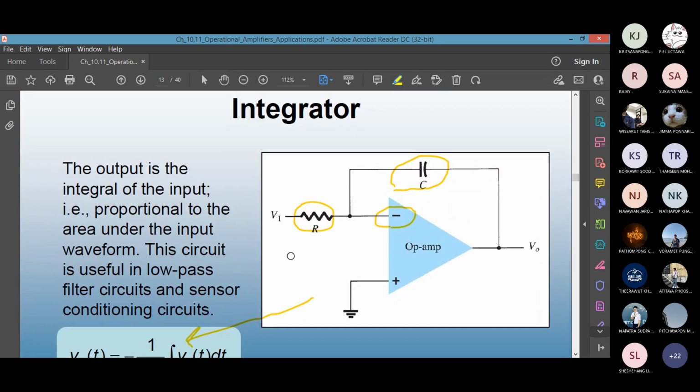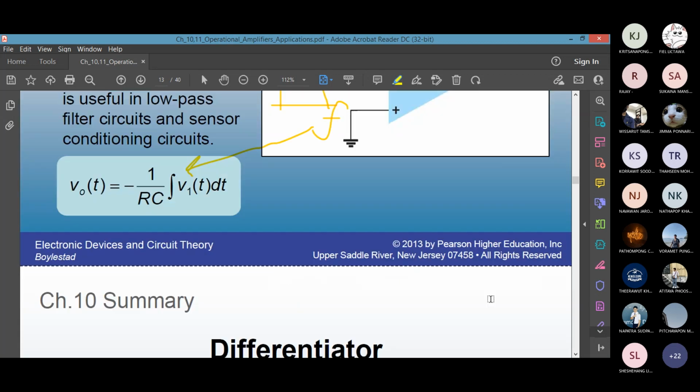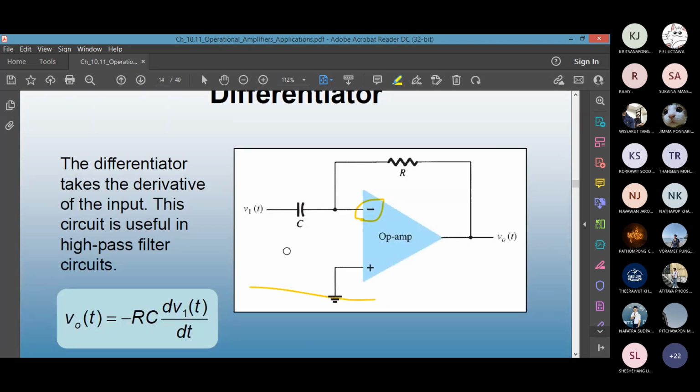For a low pass filter, it's like this. Let's say you have V out, and then you have a frequency. It may not be a linear scale; it may be a semi-log scale, usually log of base 10. For a low pass filter, you will keep getting outputs as long as the frequency is low. Ideally, it will cut off, but in real life, it will drop a bit, and then when it's too high, no more output. For the high pass filter, it's just the opposite.